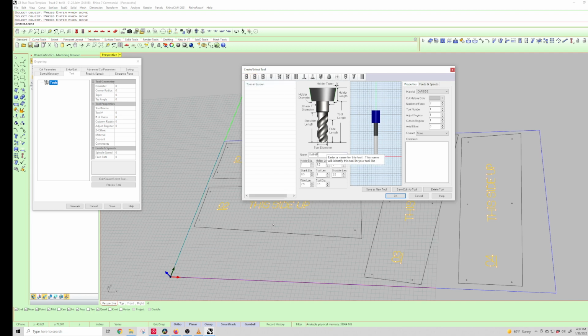So we're going to click on either one of these. You're going to name the V cutter. So we call it V cutter, and then name the tool, capital T, and then we always put our V cutter into tool number 6. You can put it wherever you want. It's just that visual that you want to have, so when you're showing all your tools, the one that I turned off at the beginning, it's going to show you what tool that is. Diameter doesn't matter because it's a V cutter. I'm just going to put 0.125 in there. And then the other really important thing, this thing is important.